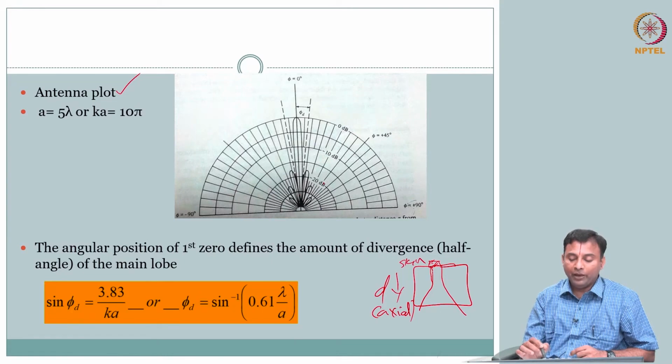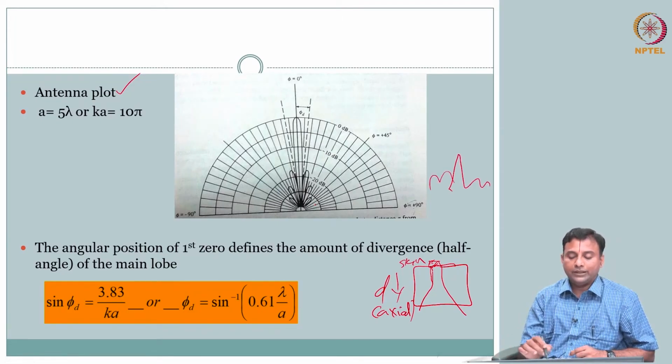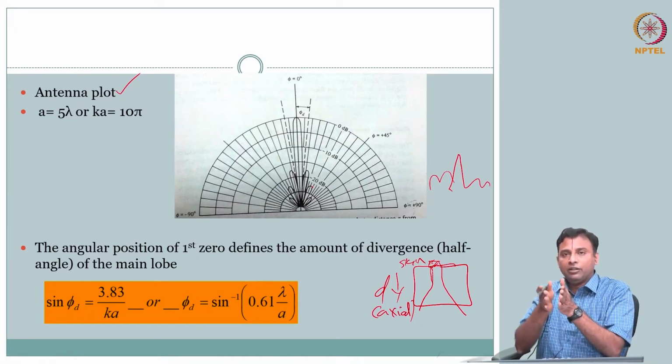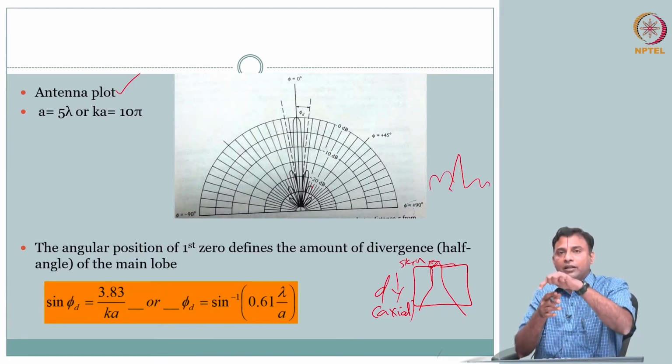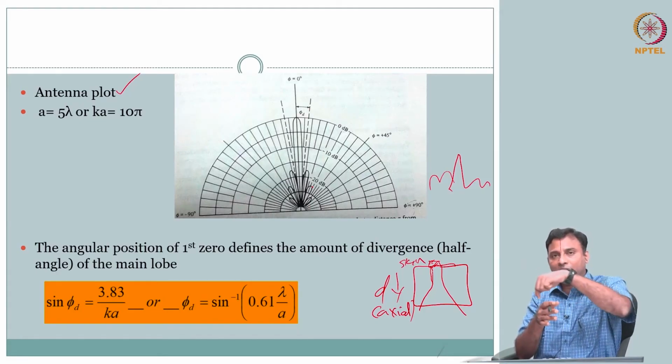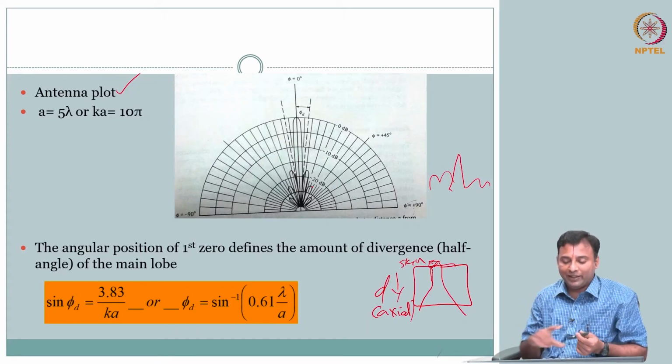So you have your main lobe. Remember how I showed there is a fluctuation in the near field? You had main lobes and side lobes. So you can see all that here. If I am trying to insonify only the front of the transducer, unfortunately, because of the size and shape of the transducer, you get different pressure experiences in the field. So there is a pattern to it. We call it the field pattern.